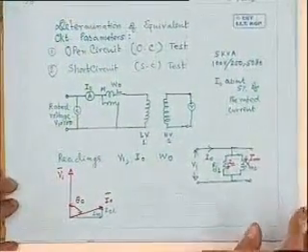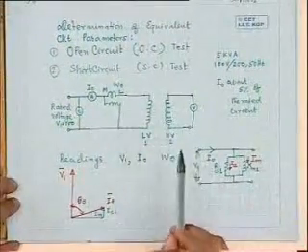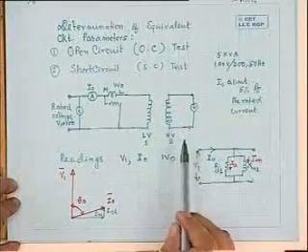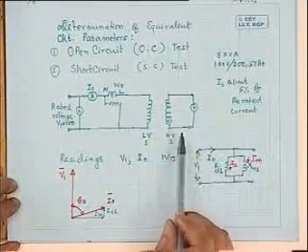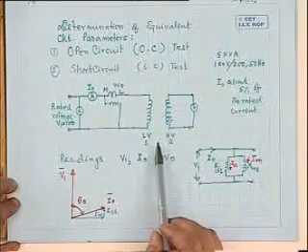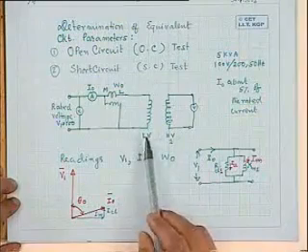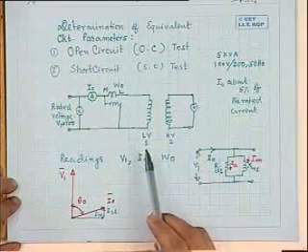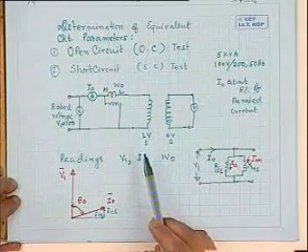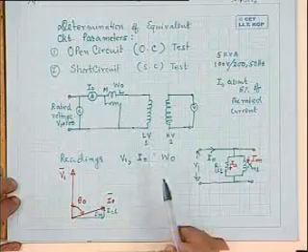Only thing is, I should like to point out that while carrying out the open circuit test, it is generally recommended that you carry this test out from the low voltage side. Theoretically, there is nothing wrong if you carry out the test from the HV side as well.